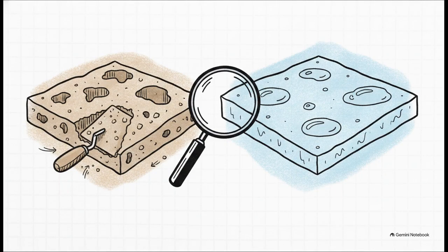When that separation happens, we call it segregation, and trust me, we do not want that. The consequences of getting this wrong are honestly pretty severe. If your mix is too dry, it resists flow. This leads to really poor compaction, leaving behind dangerous voids and a structural defect we call honeycombing. But on the flip side, if your mix is way too wet, it results in excessive bleeding. That's where the water just rises to the top, leaving you with severely weakened concrete. So our main objective? Verify that consistency right there in the field to prevent some wildly expensive construction errors.